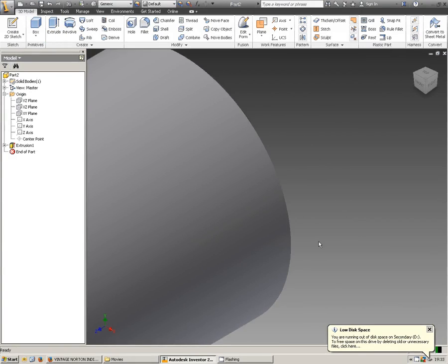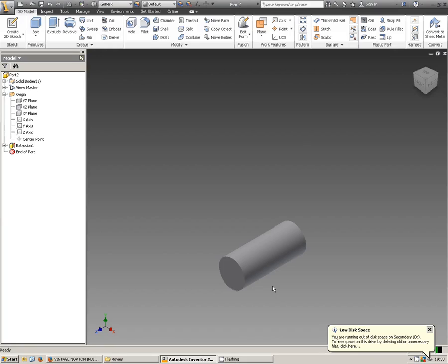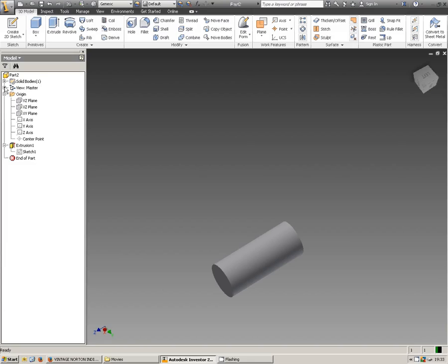Alright. So this is as far as I got yesterday evening. I tried editing the sketch and going back into the sketch and making other alterations, but nothing seemed to work. What I didn't realise was that as you add to your history of your model, you want to do new sketches. And I was trying to add to the existing sketch. So what I'm really wanting to do now is to select my next face and then create sketch.